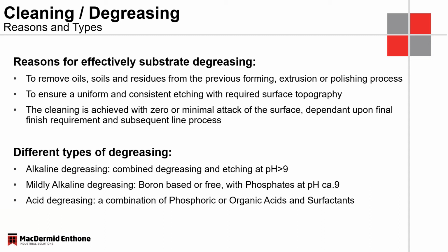The third group is the acid degreasing and the acidic cleaners. So they're mainly based on phosphoric acid, sulfuric acid, any other sort of organic acid, and surfactants as well to remove and emulsify and suspend soils and oils on the parts.